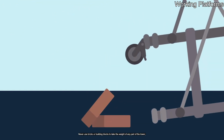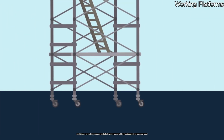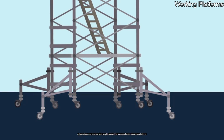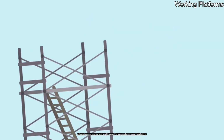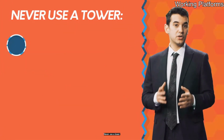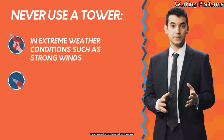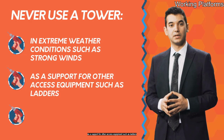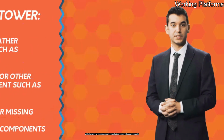Never use bricks or building blocks to take the weight of any part of the tower. Stabilizers or outriggers are installed when required by the instruction manual, and a tower is never erected to a height above the manufacturer's recommendations. Never use a tower in extreme weather conditions such as strong winds, as a support for other access equipment such as ladders, with broken or missing parts, or with inappropriate components.